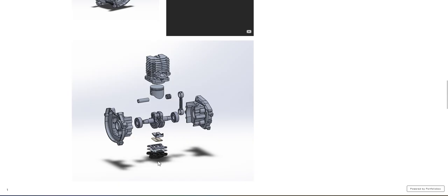These are the most important parts. All the other parts can be off-the-shelf items. Usually that's going to be made of steel. Sometimes they make it out of aluminium. The body with the fins can be made from the sand casting process for cast iron, and we can also make it out of aluminium. And for the aluminium, we can modify the shape to be able to work with the die casting process. There are blocks made from aluminium, and I think you can see that in most motorcycles.